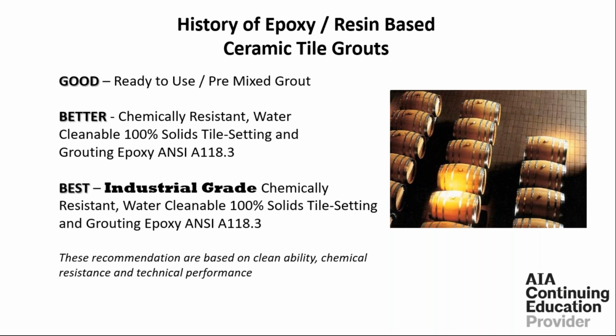On your reaction resin grouts or epoxy grouts, ready-to-use, pre-mixed grouts are good. Remember, you'll see a lot of advertising that says it has characteristics of an epoxy. Check with the manufacturer as to what they really mean. What are they telling you it'll do? Some of the characteristics of an epoxy: it may stand up to ketchup, Coca-Cola, coffee, urine. But will it stand up to harsh cleaning of 100% solids epoxy? Find out before you just jump into these ready-to-use type grouts, thinking that they're going to perform like an